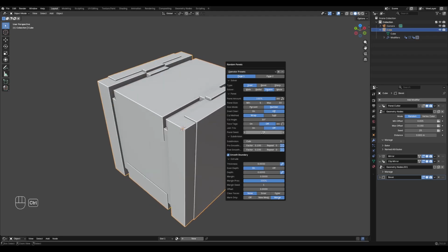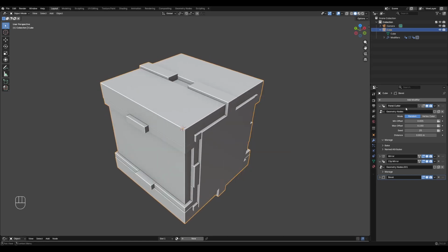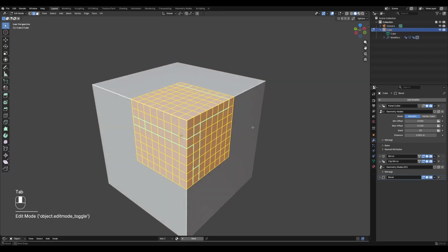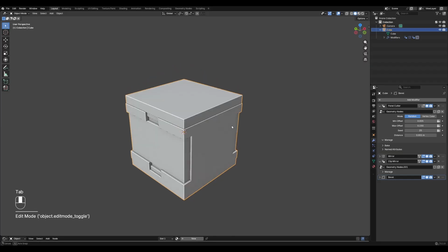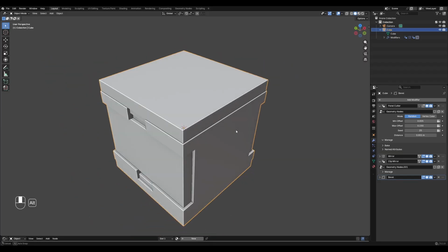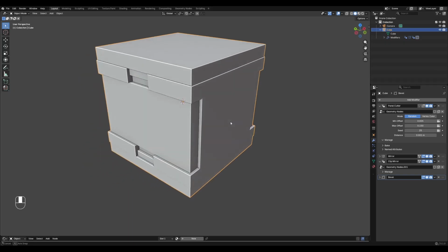And everything is non-destructive. All the extrusion depth is generated using the panel cutter GeoNode system. All we're doing is changing the pattern of the marked sharp edges using the random panels operator in random flow, as you can see here. And we can also go to vertex color. However, this will not work with random panels anymore because you need specific vertex color for the different face islands or face groups.